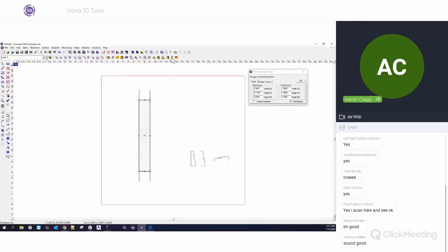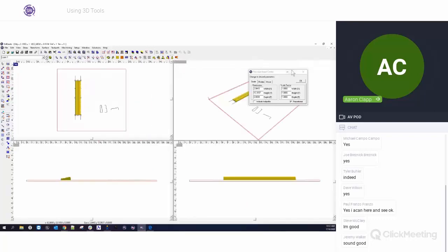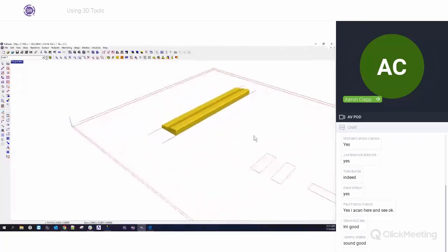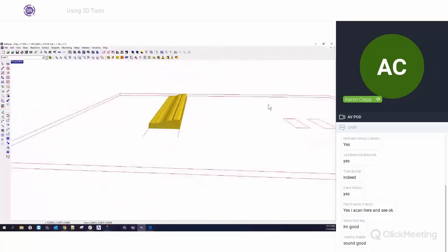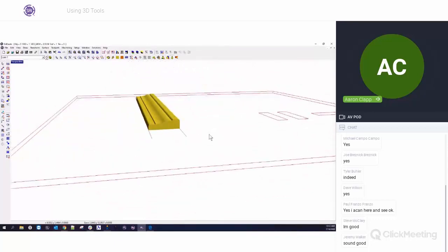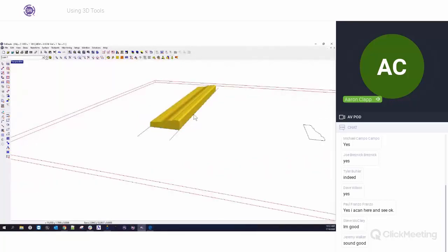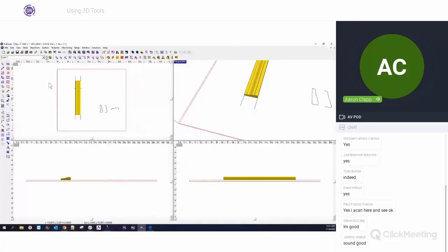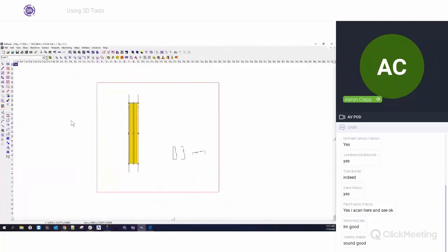Once I've done that, I'm going to turn on my light bulb to see the rendered preview. And I'm going to go to my perspective view and get my thing out of the way there. And just like that, now we've created some molding in the same shape of what I had over here. So just like that, I can very easily and very simply create crown molding. I could do this for arched sections, curved sections, square sections, a bunch of different ways. So that's your simple sweep to rails. Very, very simple, very, very easy to use.